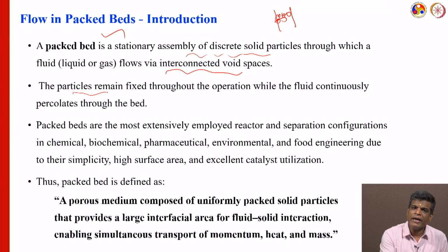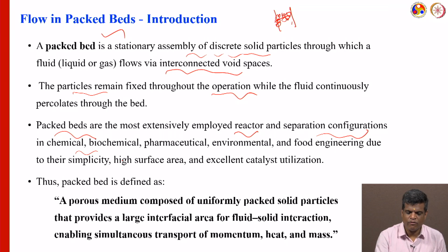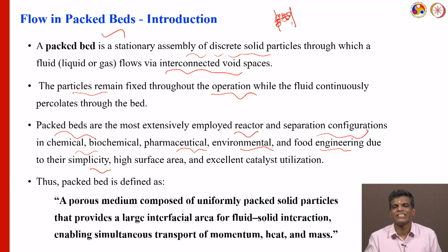So the particles remain fixed here. That is the difference between a fluidized bed and a packed bed. In the packed bed, the particles remain fixed throughout the operation while the fluid flows continuously through the bed. Packed beds are the most extensively employed reactors and separation configurations in chemical, biochemical, pharmaceutical, environmental, and food engineering, because they are very simple, we can always use a high surface area, and we can achieve excellent catalyst utilization here.